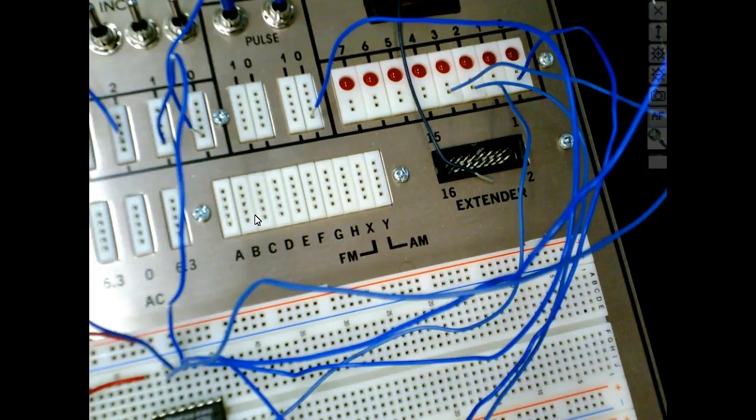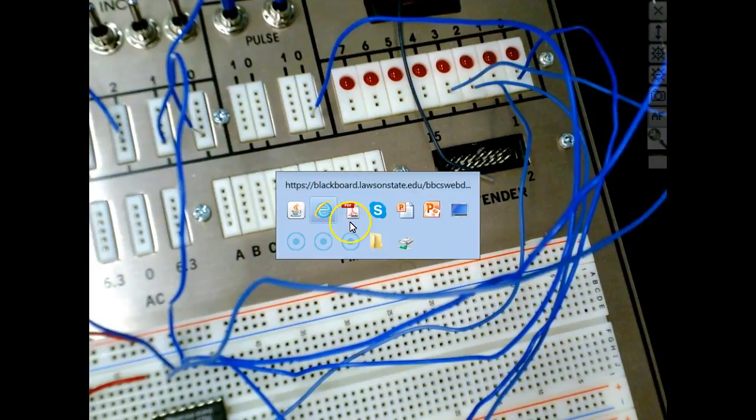So what is the output of the 74147 supposed to feed? I'm on page 98. Are y'all looking at schematics, right, with me? What's the output of the 74147 supposed to feed? It's supposed to feed a bunch of inverters because the 74, why do we have the inverters? Why do we need to switch it over?